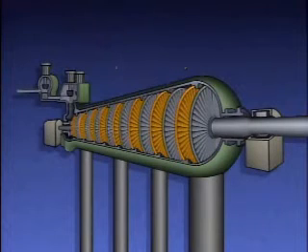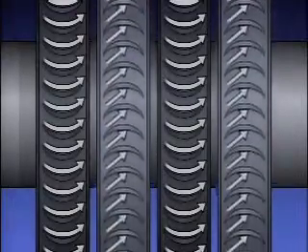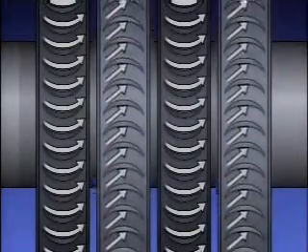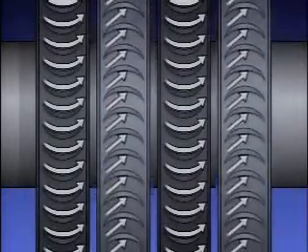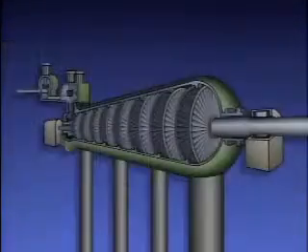The distinction between diaphragms and wheels is the way they function during turbine operation. Diaphragms are stationary and their blades are fixed in position. Their function is to direct the flow of steam leaving one set of rotating blades into the next set of rotating blades. Wheels, on the other hand, are moving parts. They are designed to turn as the steam flow passes through their rotating blades. The rotation of the wheels turns the shaft and the generator.